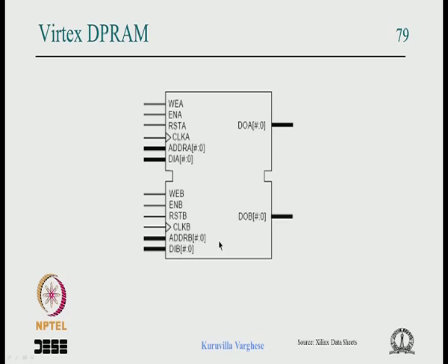If it's a single port memory, this computation block has to write and then stop, then the computation here has to read using the same port. So the throughput will suffer; the dual port will allow you to write and read at the same time at different locations.